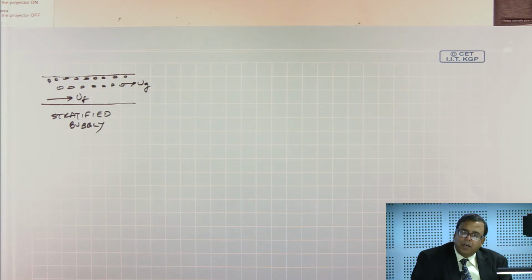And so, therefore, there are 100 different correlations out there, and each of them is very limited in its scope. The first limitation is you have to know, before you use it, what flow configuration it was developed under. Then it might have limits on the validity of the Reynolds number, and you are dealing with two different Reynolds numbers: Reynolds number for the liquid, Reynolds number for the gas. You have to be aware of the limits of both of those under which the testing was done, and your results are only valid for that range of Reynolds number and for that diameter tube.